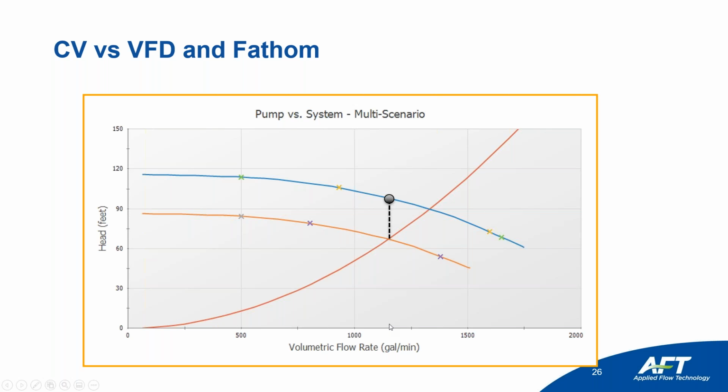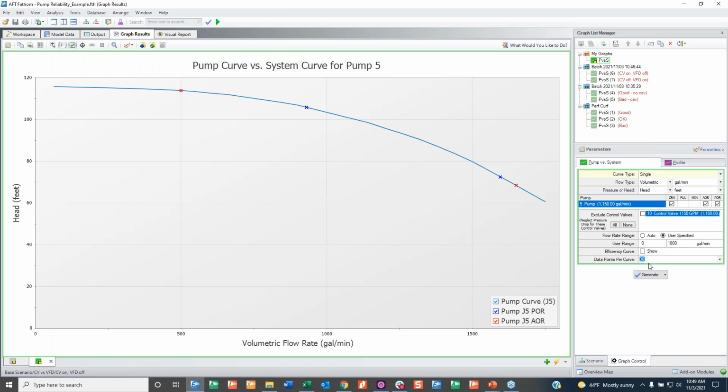So the control valve topic in graphing is very confusing. It's because really to generate a system curve, it assumes many different flow rates, but like you got a control valve, so there's not really many different flow rates. There's one flow rate. So you model it without the control valve. If there's a single path, you have to do that, in fact. And right here is where that will operate. So you have to know what your flow rate is, and you can assume the pressure loss there across the valve. So sorry about the graph.